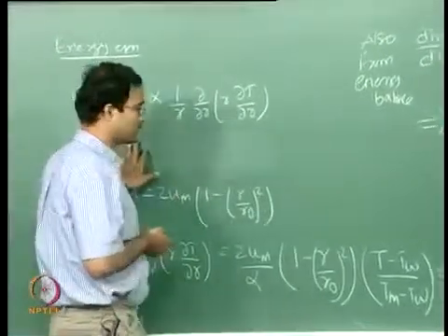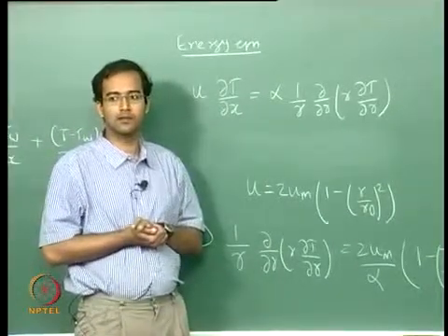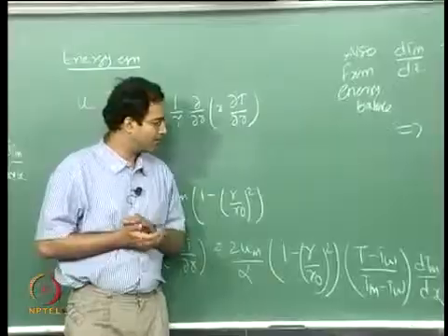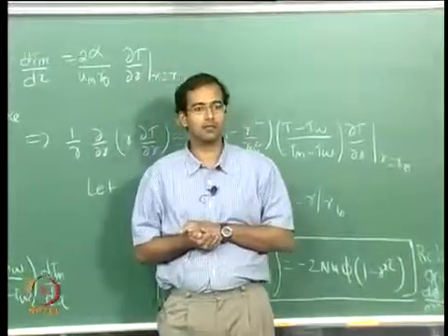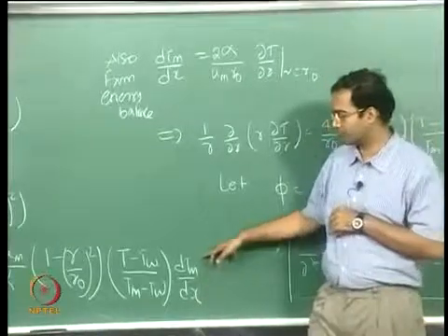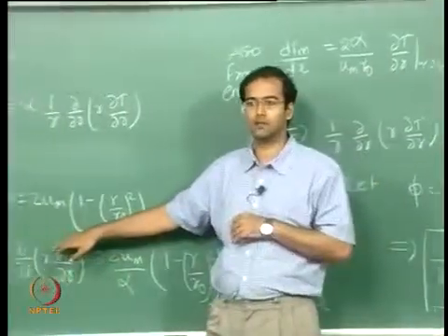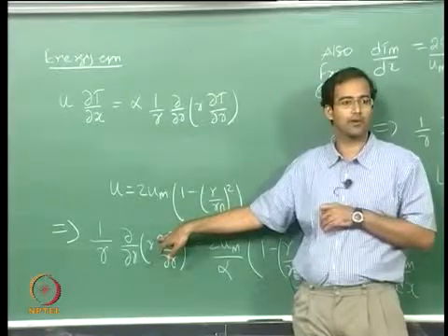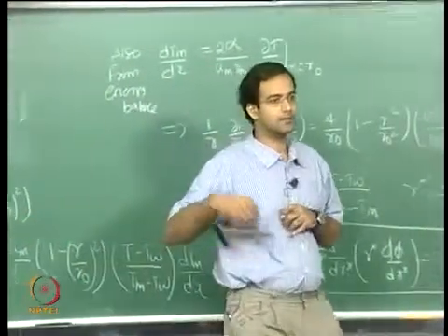Okay. Also, since we have already calculated the velocity profile, which is a parabolic profile, we have substituted the parabolic profile into this expression. Now what is the problem with this? Unlike the case of constant wall flux boundary condition, there your dTm by dx was a constant. So this side was not there, you had only dTm by dx. This side it was T as a function of r, so you could directly integrate this. This was integrable straight away, and you can find the temperature profile with respect to r and apply the boundary condition. Okay, so that was a very straightforward way.